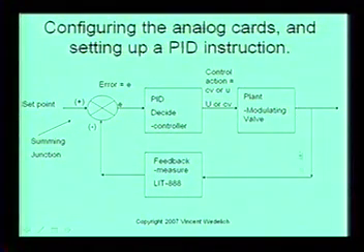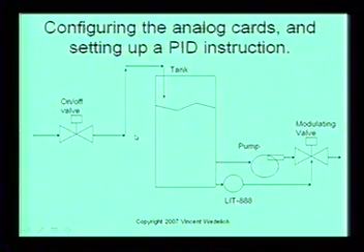And you can see this is a closed loop feedback, and that's how we'd have that. So we've closed the loop. See how we're closing the loop. The measurement point is actually controlling the modulating valve. Now, in reality, you'd say, oh, wait a second, why don't I just tie the level indicating transmitter to the modulating valve? Well, that's not going to work. You actually need to have a controller in here.